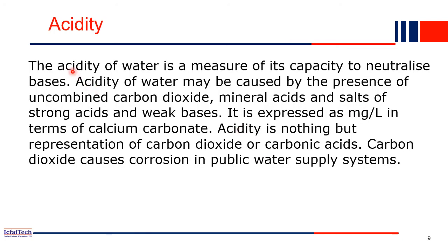Now the next property of water is acidity. The acidity of water is a measure of its capacity to neutralize bases. Acidity of water may be caused by uncombined carbon dioxide, if present, or by any mineral acids present in the water. That causes acidity in the water. It is expressed in milligrams per liter, that is, how much acid is there per liter in terms of calcium carbonate. So acidity is nothing but the representation of carbon dioxide or carbonic acid present in the water. If water is more acidic, then it will harm our human body system, as well as some industries.